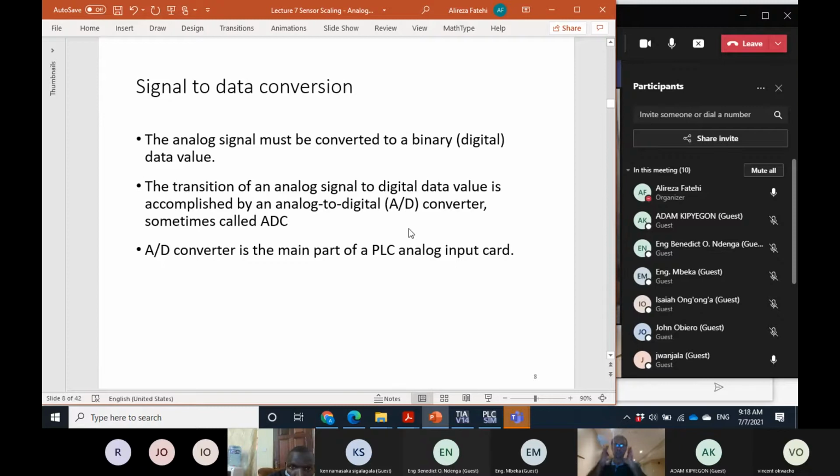That voltage is transmitted to the PLC, and the PLC reads that. In fact, the PLC works as a digital voltmeter, or if they supported current signals, a digital ammeter, but here a digital voltmeter.